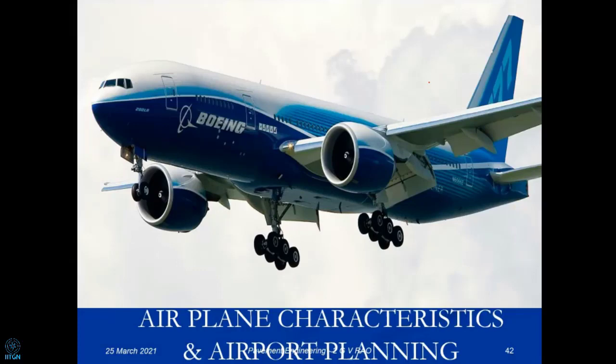So, how do we classify these loads now, or the wheel loads, into actual design of the aircraft as well as the pavement now. So, these are what we call the rear wheels actually, or the main landing gear, because there is one set of wheels on one side of the aircraft, below the wing more or less, and another set of wheels on the other side actually. So for every landing gear, there are two sides now. In this case, the landing gear consists of, you can see on one side 3 plus 3, 6 wheels, and other side 3 plus 3, 6 wheels. So that means main landing gear has got 12 wheels actually, and the nose gear usually a single wheel.